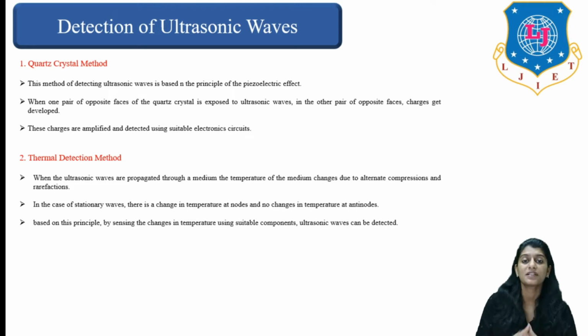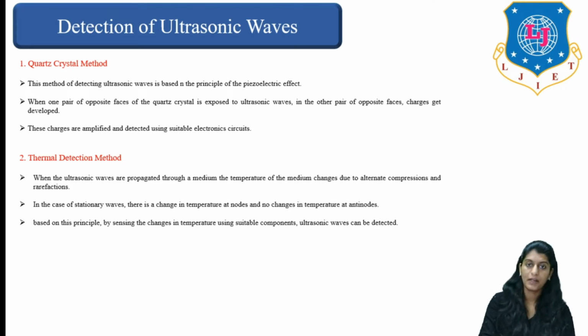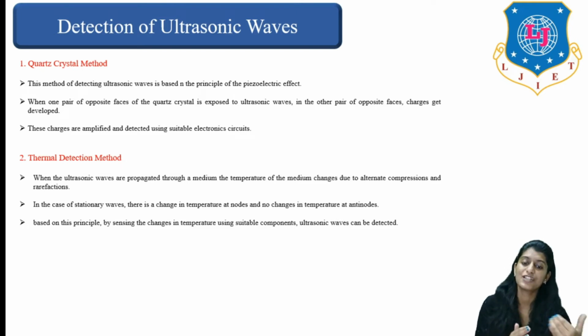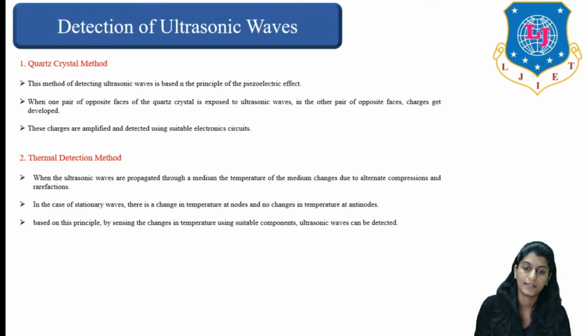In the quartz crystal method, it is based on a principle similar to that of the piezoelectric effect. When one pair of opposite phases of quartz is exposed to ultrasonic wave, then in the other pair of opposite phases, charge will get developed. What we are doing is using 2 different quartz materials, one for generating ultrasonic wave and one for detecting ultrasonic wave.